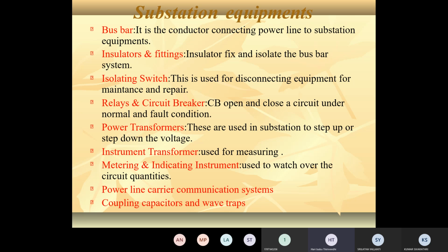Now coming to relays, these are also protecting equipment, installed for the protection of equipment against faults and overloads, mainly overloads. Where overload occurs, on the load side, we utilize protective relays to compensate for those overloads. A protective relay detects the faults and initiates the operation of the circuit breaker.